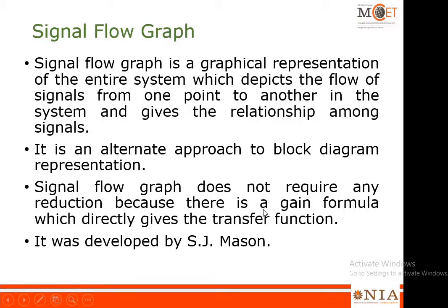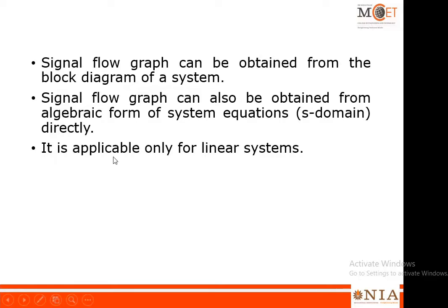So here you've got a formula called Mason's gain formula. Using this formula, we will be able to calculate the transfer function of signal flow graph directly. This formula is named after the person who developed the signal flow graph, S.J. Mason. We can obtain a signal flow graph from the block diagram as well as from algebraic equations defining the system. Algebraic equations, I mean the frequency domain equations.